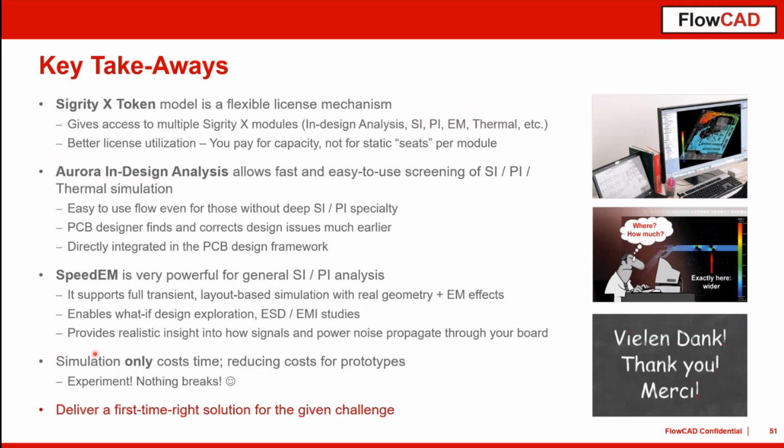Only at the moment when you run the simulation is it blocked. Since the analysis mostly takes only a few minutes, your colleague maybe has to wait a few minutes until he also wants to simulate something, but I think that should not be a breaking point to use these licenses. In principle, you can run as many PCB editors in parallel as you want, and just in that moment you run the simulation, it is blocked, and it is free again when the simulation is done. I hope this answers the question.